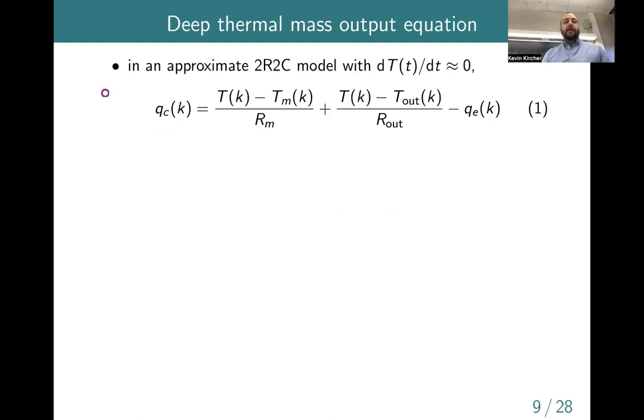All right, so where does that come from? Well, you may remember we came up with these battery models for buildings by doing kind of a 2-timescale approximation. So we said, well, there's kind of 2 characteristic timescales, a fast one associated with the light or shallow thermal mass, and then a slow timescale associated with the heavier, deeper thermal mass. And we made 2 different assumptions that led to basically a fast battery for the shallow thermal mass, and then a slower battery for the deeper thermal mass.